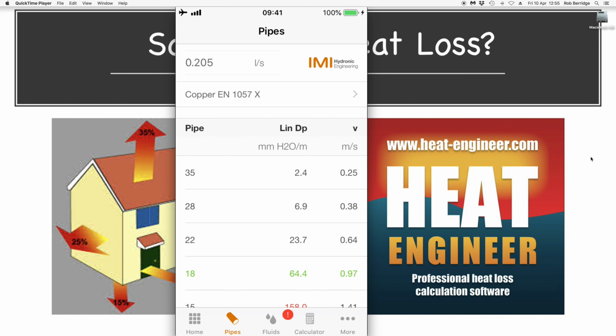You will, and everybody's noticed it. If your flow rate is too high on a combination boiler, you'll get system noise. You'll get clonking when you turn the taps on and off, water hammer, that kind of thing. So you put in a shock arrestor, etc., those kind of things.